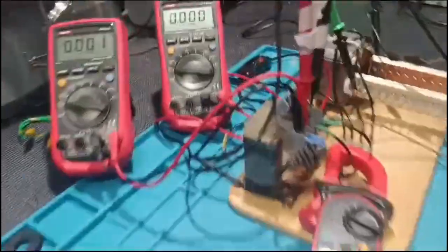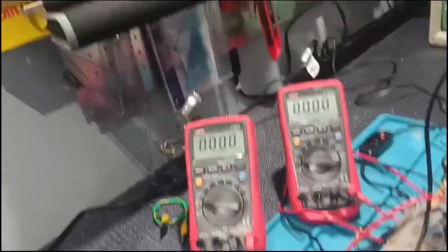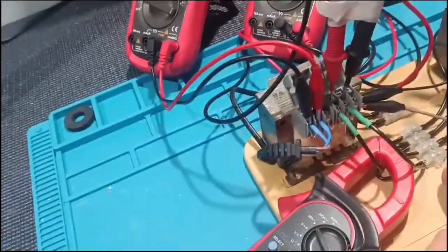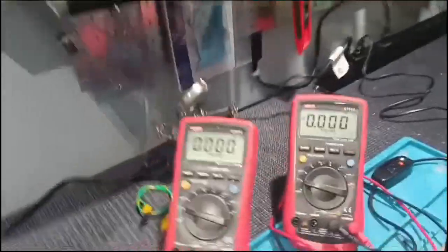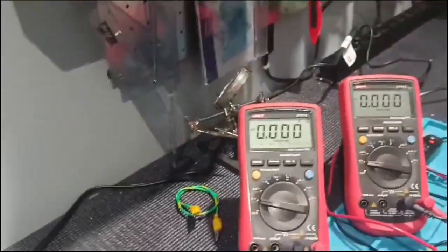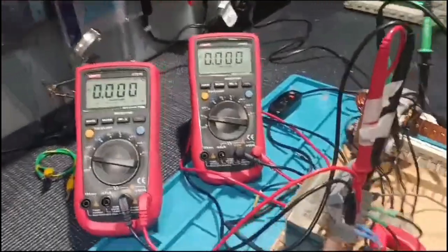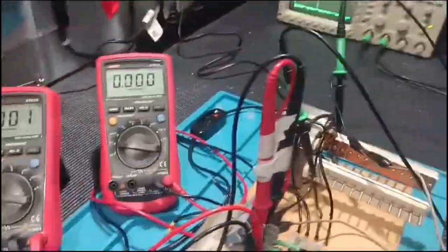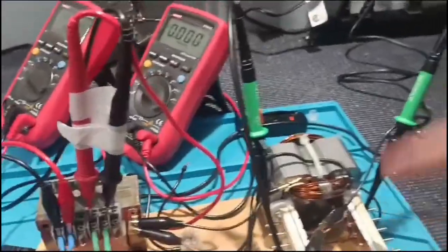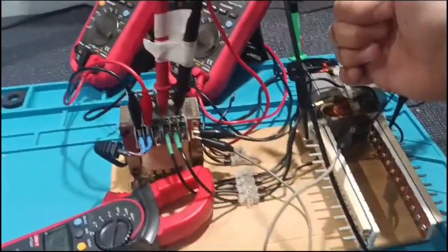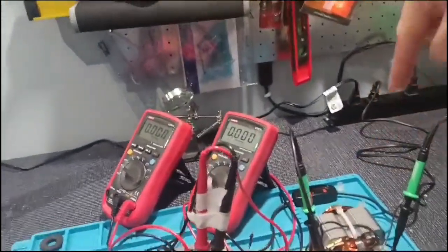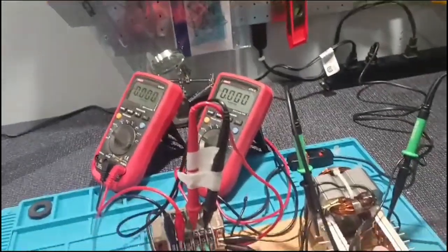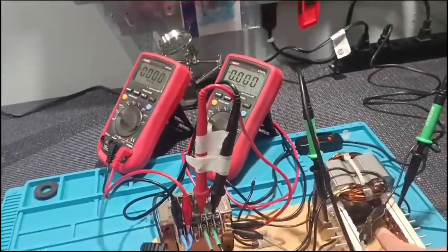So, now we have the parallel configuration. We have the same two measurement tools, the same components, but a different connection. This time I'm using the parallel connectors right here, okay? And we are taking the measurements by using the oscilloscope and the multimeter for the input at the transformer and the output. Moreover, we have to pay attention when we create the connections, because we have to make the magnetic field in such a way that both coils generate the same magnetic field in terms of sense, right? It has to be the same sense, so both create a magnetic field that goes down or up. Otherwise, the magnetic field will be cancelled in the middle of the chamber.